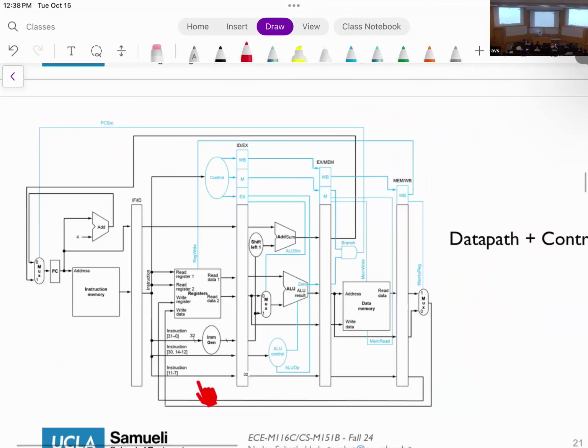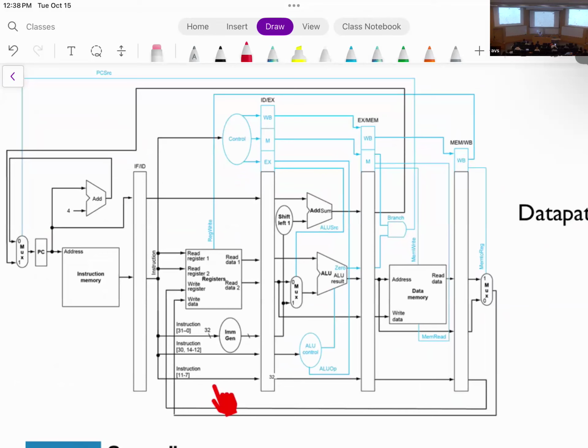As you can see, all of your instructions and everything is also being pipelined. Not just the control signals, but your data is also being pipelined. So for example, this is your PC. Your PC is being pipelined and goes through this process. And this was the adder that we were using for PC plus offset. You can see that this is still PC, so this wire and this wire are exactly the same. We just pass it through the clock cycle. Now, since there are 2 registers in between, the value here is the PC for this instruction, versus the value of PC there, which is the PC for the third instruction.